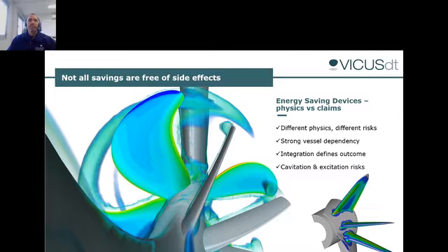But to get this small percentage, you need to be very sharp on the hydrodynamic analysis, on the operational conditions in terms of speed, drafts, and powers, also on how to choose the best technology for your project based on the constraints you have, and also what are the potential risks in terms of the cavitation on the ESD, cavitation on the propeller, or what excitations are being generated.